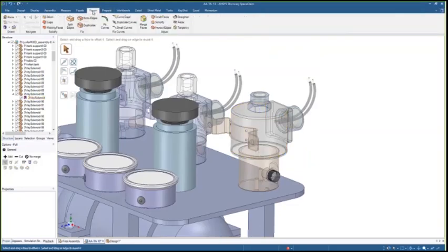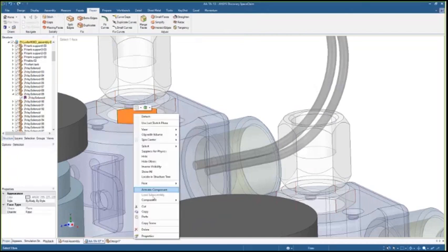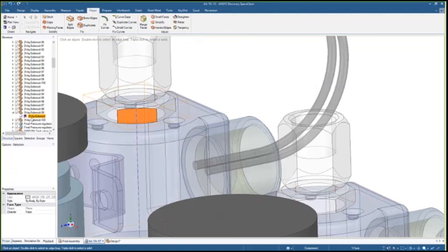So there's a set of tools in our Repair tab designed to solidify surface bodies. If there are multiple bodies that we need to join together, the stitch tool will do that, and it actually found some. These edges are not joined together into one body. If I were to find this in the tree, oops, we found it up here.